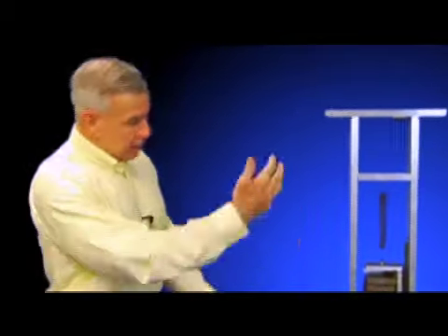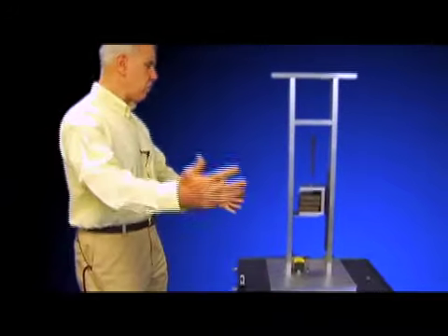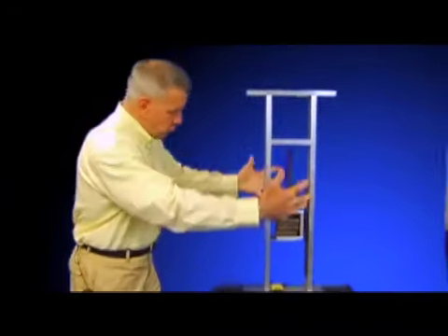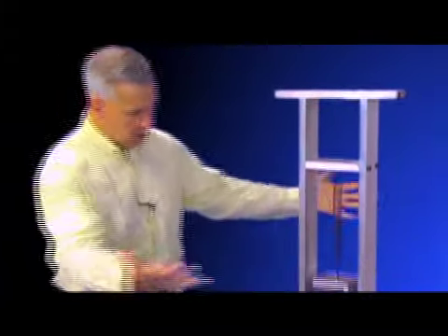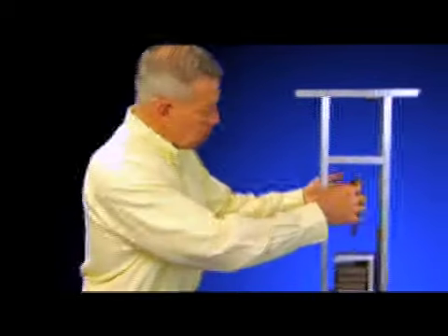So what simplifying assumptions might I make for this dynamic physical system? Well, let's start. The structure mounted on this table, I'll assume, is a rigid structure. Nothing, of course, is rigid, but I will assume that, which essentially says that the environment, the surroundings, are independent of any system motions. Well, as I move this, the structure may wiggle and wobble and the table may shake, but I'm neglecting that. The spring.